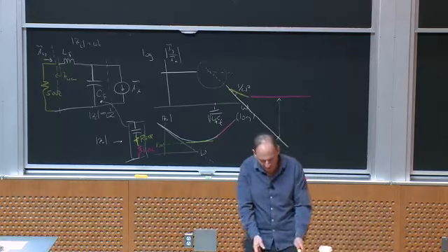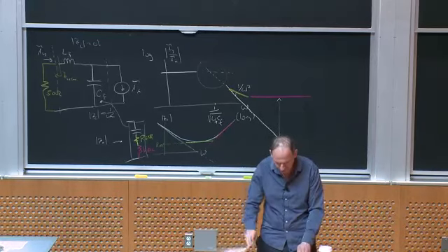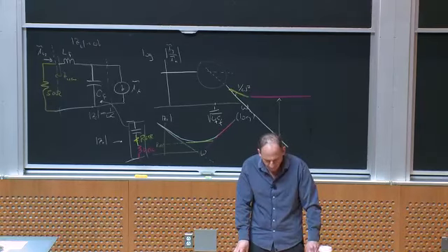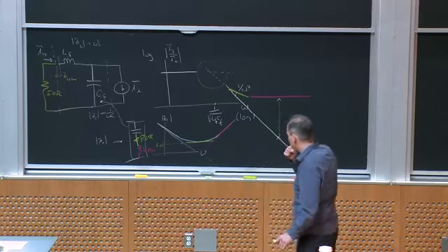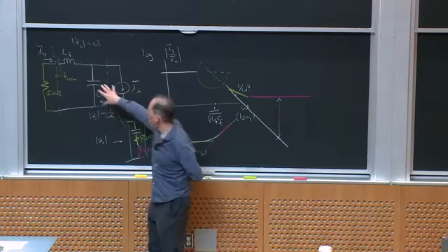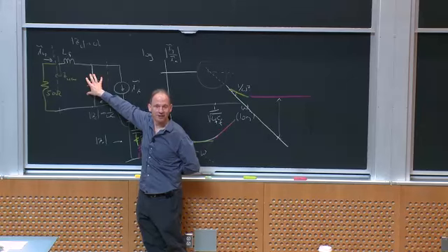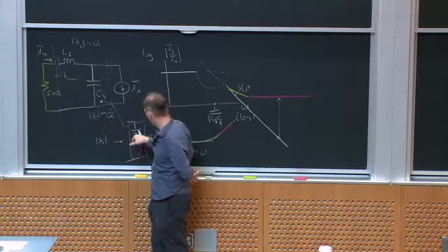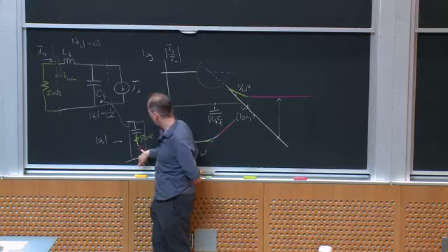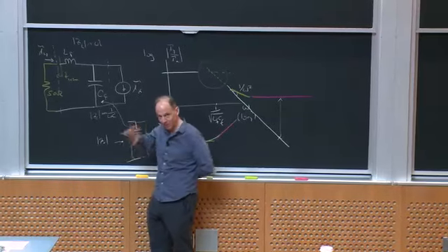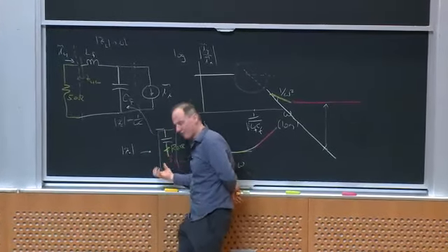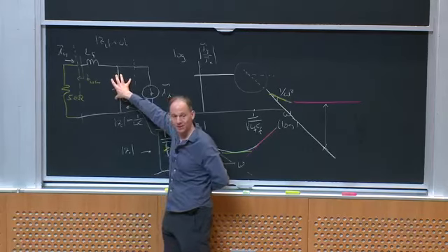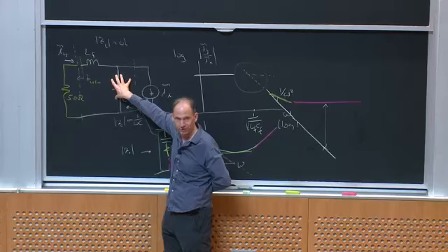So, that's kind of a problem. Okay. What would I do about it? What I might do about it is not just have one capacitor, but have a bunch of capacitors, some of which might not have a very high C value, but they don't have as much inductance, and so they look better at high frequencies, and then bigger capacitors that have better performance at low frequencies, but not as good at high frequencies. So I can certainly do it by being careful about how I pick this component, or picking multiple components to cover different frequency ranges.